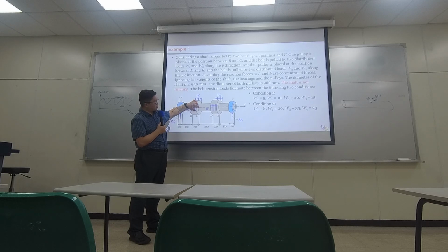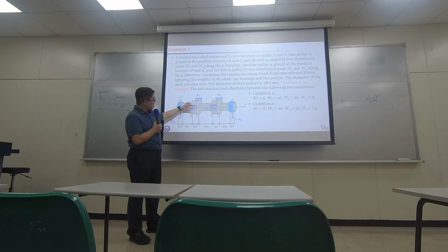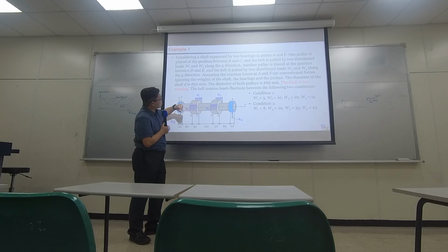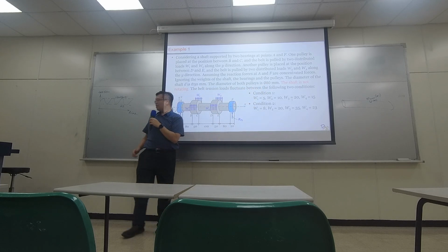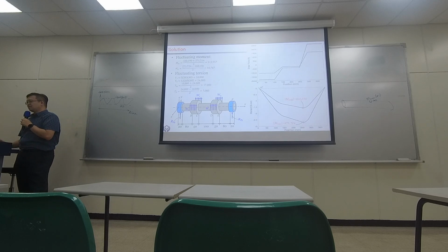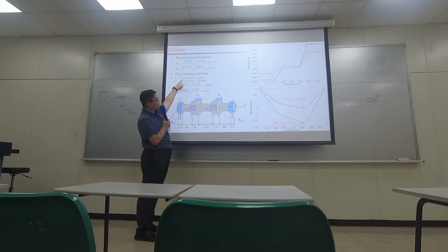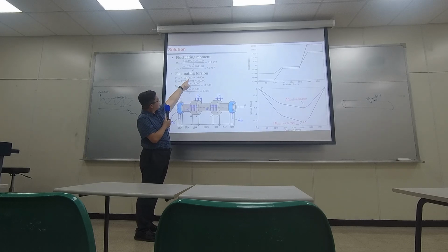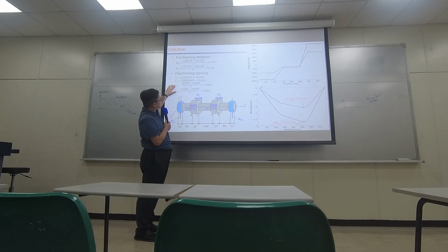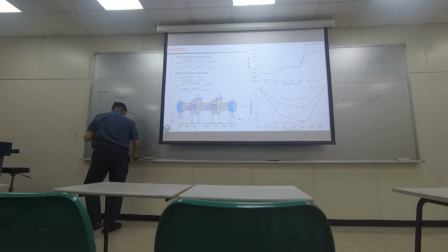And multiplying the radius, you have the moment. At the time, I multiplied by the radius, and the radius was 40. So this is the difference of W's, this is the distance, and this is basically the radius. From here, you can see I directly used it to represent the torque inside the shaft.